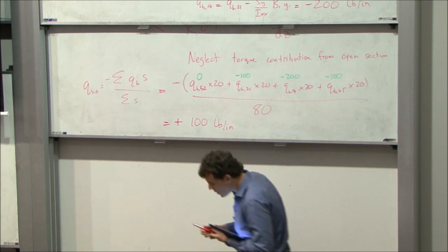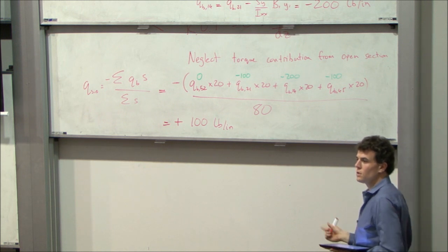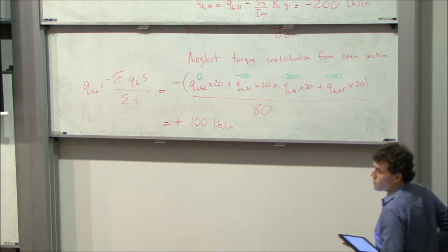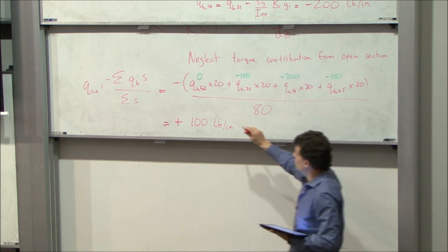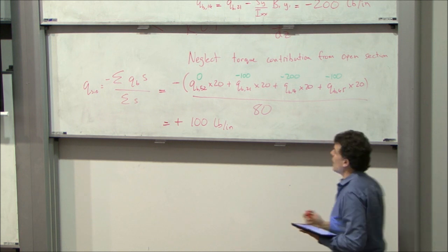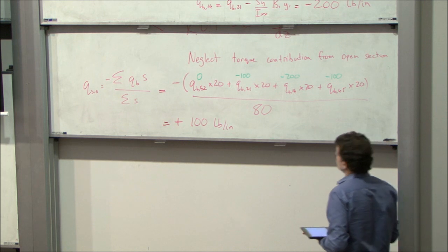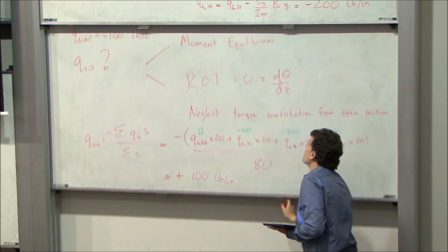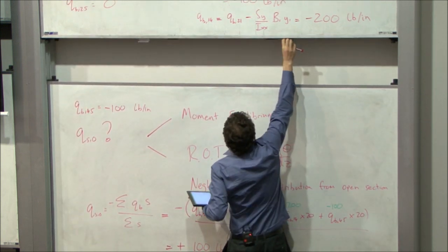Now what does the plus sign mean here? Which direction did we do our calculations in? In an anti-clockwise direction around the loop. Okay? So because we did this in an anti-clockwise direction, QS0 is also going to be in an anti-clockwise direction. So we can add that to all the other QBs that we have up there to work out our actual Qs. Actually, I'll put that one up.